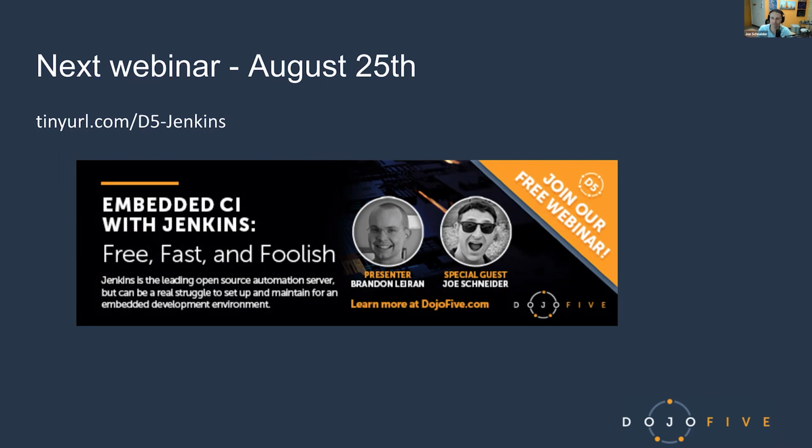Michael had one extra. We've got one more minute, so maybe we can answer it real quickly. The one question that's still outstanding is, what stage of development would you recommend testing or setting up HIL? At the very beginning, the earlier the better. As soon as you have hardware, right? You can't set it up before hardware, but you can think about it before hardware. So design for it. Exactly. The earlier it comes to your mind, the better, if you know that you're going to need it. Because usually when you do it mid-project, it takes more time to set up and it takes more resources to make it work.